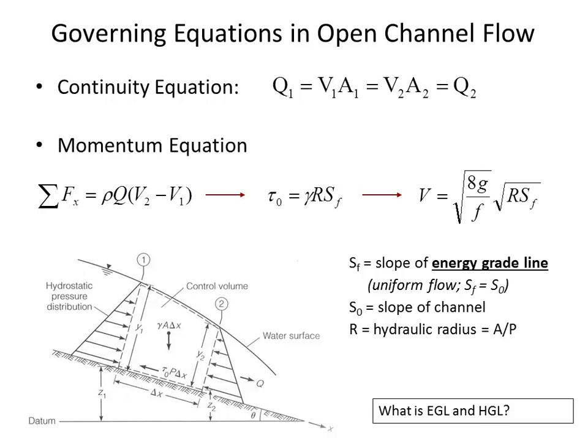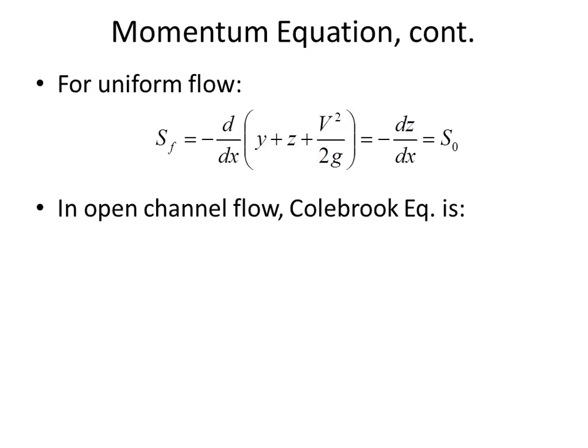And so finding the new depth isn't as easy as saying, well, I know the depth here, and there's some one slope between them. It's going to be us breaking it up into little pieces and treating a curve like a series of straight lines in order to find the new depth. That's to give you a glimpse or a preview of some of the numerical methods we're going to have to utilize to find the slope of the energy grade line's effect on depth.